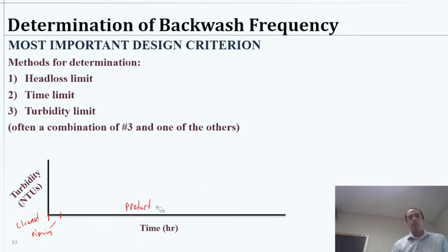Let's do this. So we'll have this production time. Ideally, that's clean water. And then at some point, we have a cutoff where we say, all right, well, now we need to backwash and clean again. Okay, so that's our total cycle lifetime, and then it repeats, right? So that's why cleaned, that's the same as backwash, right? So we can repeat those cycles like that. So if that's our system, and this would be the cycle end,